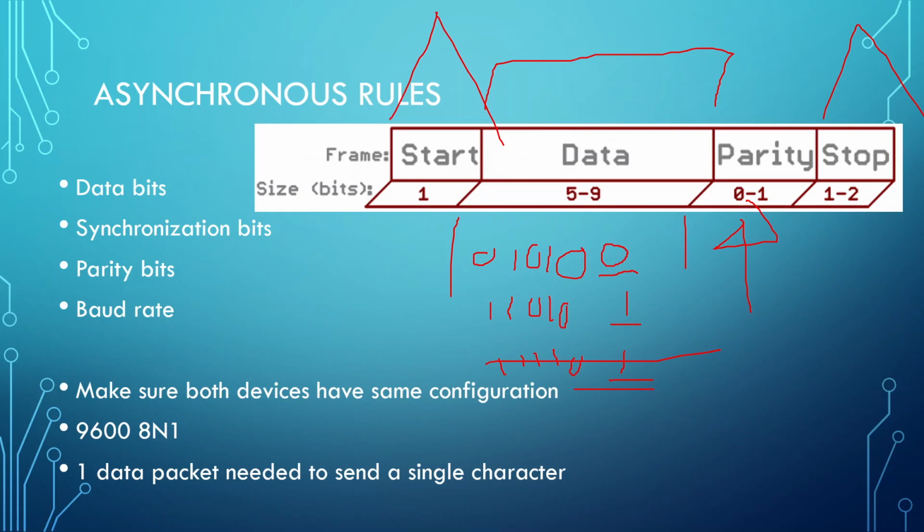Mixed up baud rate is probably the one that's going to happen the most. You're going to plug a new device in, and it's supposed to be this baud rate, and it's not, or you had your old baud rate set high, you plugged it in, and you're like, oh, that's the default, 9600, perfect, plug it in, it did work. And when you do that, you get all sorts of weird data. One of these days, I will show you guys.